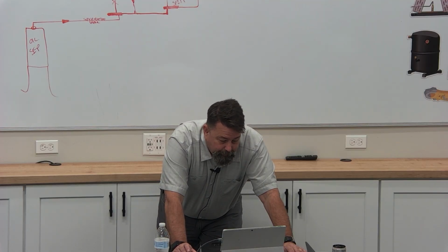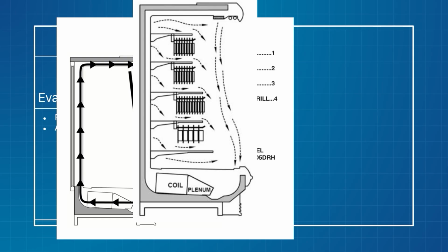If I've got piping through here, which I will, right? Make sure it's not interfering with this plenum sitting flush on the bottom and sealing to this pan. My coil, so my fan is going to be mounted in this plenum. It's going to suck in and blow across this coil. And my air, as we can see here, wants to go up this back wall.